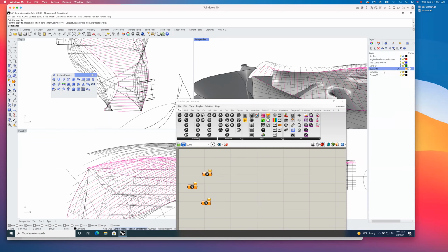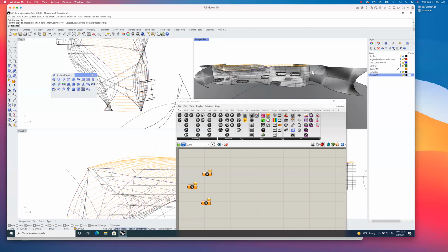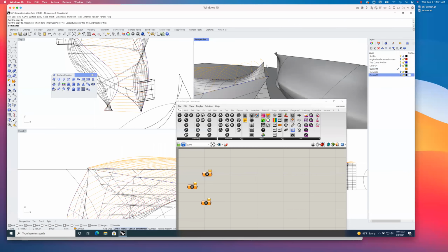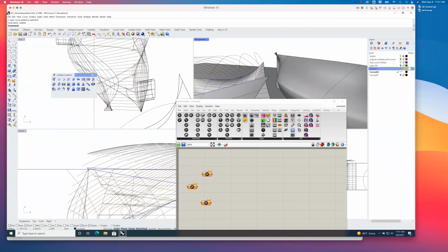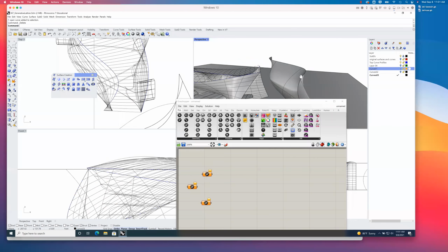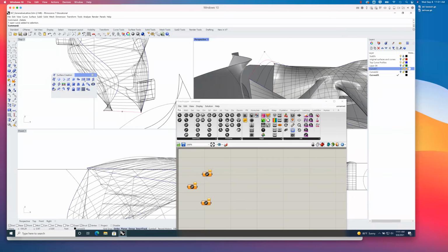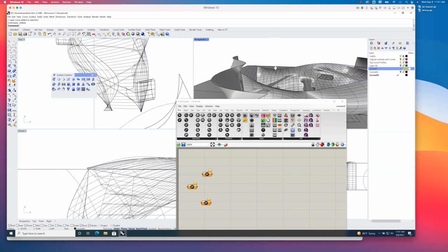So now I have, turn these layers off, and you'll see I have curves 01, which will be all of the left bottom chords. I'm going to turn off this right bottom chord at the end. Then I have the top chords, curves 02, and then you'll see this here in a moment. Here's the left chords. The curves 03 will be the right chords. Okay, so I'll turn those off, and I'll just delete this bottom left chord there.